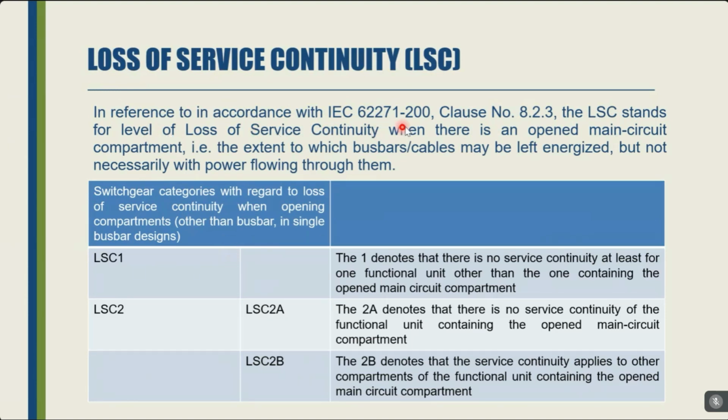In reference to IEC 62271-200, LSC is loss of service continuity. So this is another new concept. LSC is loss of service continuity when there is an opened main circuit compartment. If the main compartment or the main circuit breaker is opened, there will be a loss in service continuity, so the downstream of your system may have a discontinuation of the power service. This is done to understand up to which extent the busbar and cable may be left energized, but not necessarily with power flowing through them.